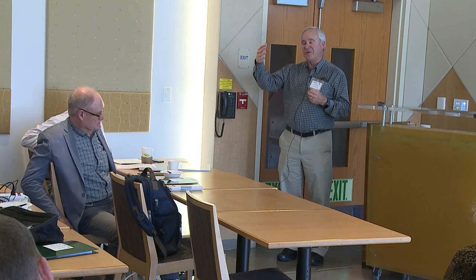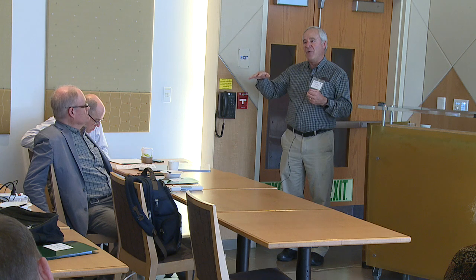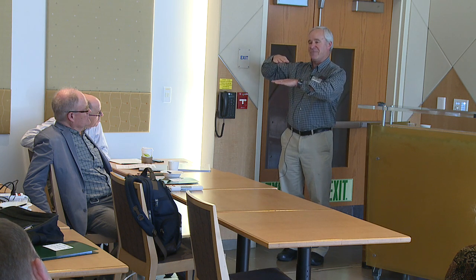We just did the San Francisco Museum of Modern Art, and on that one, it's very tight humidity. So we just make it so that the air is saturated coming off the cooling coil all the time, either with the cooling coil itself or with basically a direct evaporative humidifier, direct evaporative cooler. The air is always coming off at 52.5 near saturation, and that puts it right in the space automatically. So we don't even have to measure humidity at the zone level. We do because they need it to prove that they're maintaining their humidity. But we don't have to. It actually maintains it by itself.